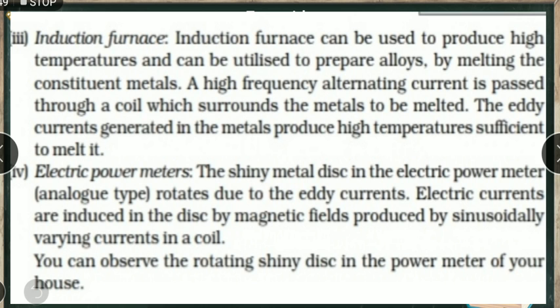So when these metals are present in the furnace, what happens is, at each and every face, the surface of the metal, a high current will be generated. The current is nothing but in the form of eddy current. You know that if current has been generated, the electric energy will be in the form of heat. So finally it melts.